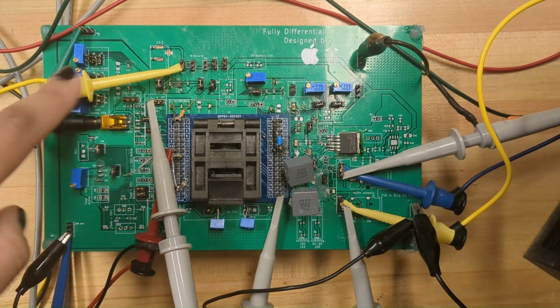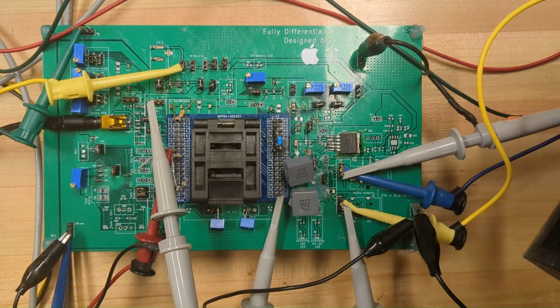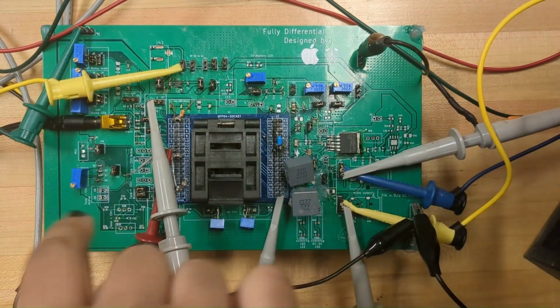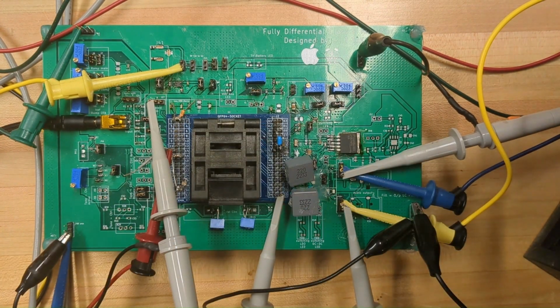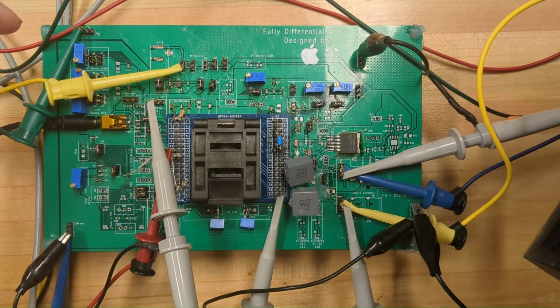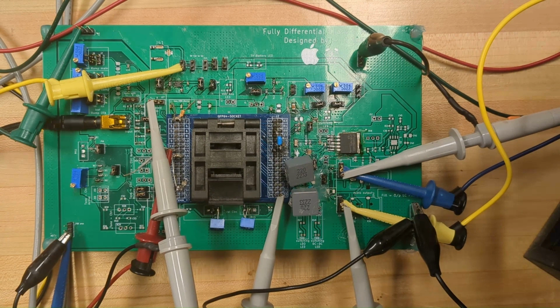Over here we have some tone control circuitry, and there are multiple potentiometers which help tweak the IREF going into various blocks on our chip, and this essentially helps us control the performance of individual blocks on our chip. For example, the IREF going to the ramp generator helps control the ramp frequency.